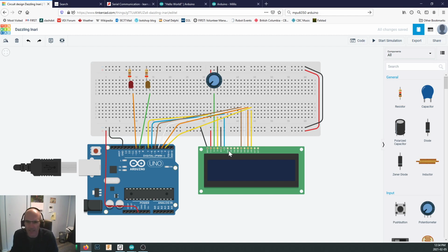And what we've got in here is a whole series of switches to help support them: the read, write, and the enable pin. So what happens is that when we talk to this screen, we set these bits either high or low the way that we want them. And then the enable pin says, okay, I've set all the bits, and I turn on, and then this chip reads 4 bits at a time.